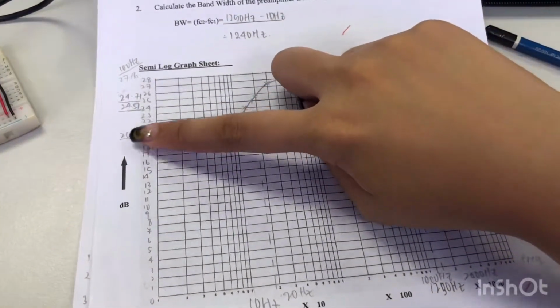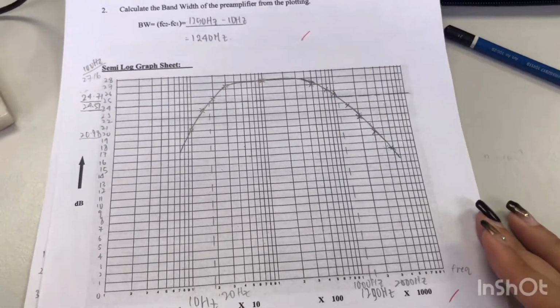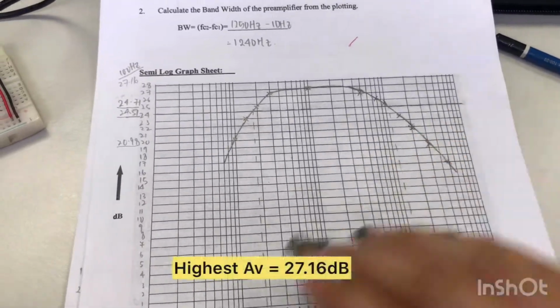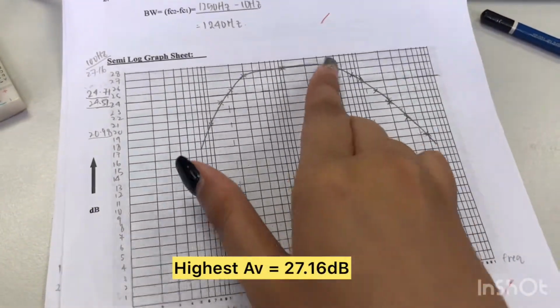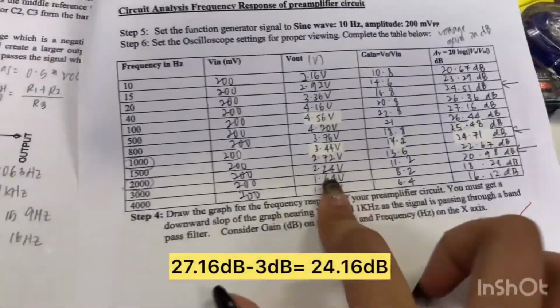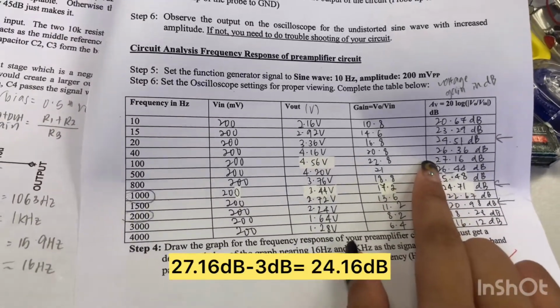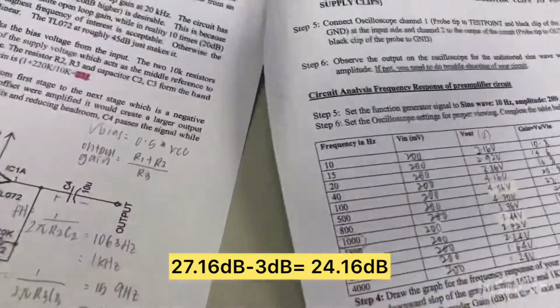So now we're going to find the bandwidth. The highest voltage gain in this case is 27.16 decibel at 100 Hz. So 27.16 decibel minus 3 decibel is 24.16 decibel, and that is the passband gain.